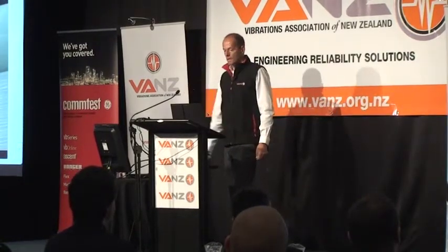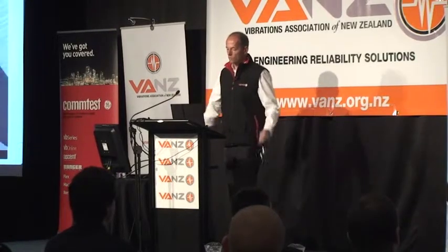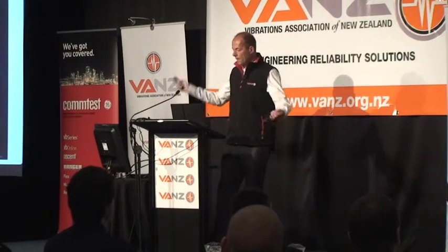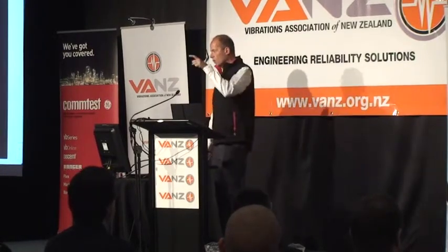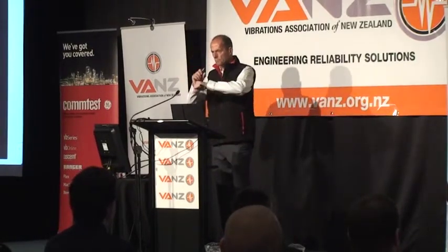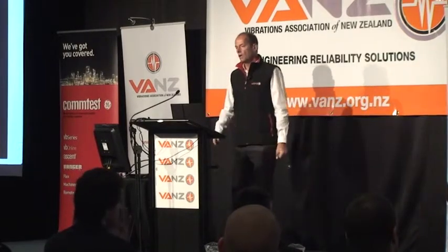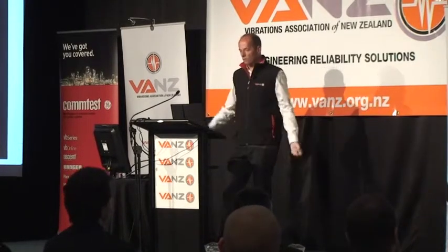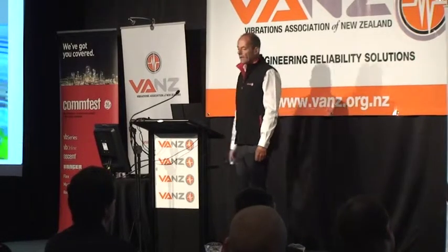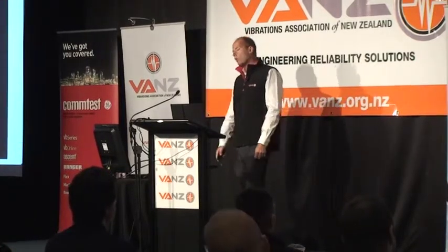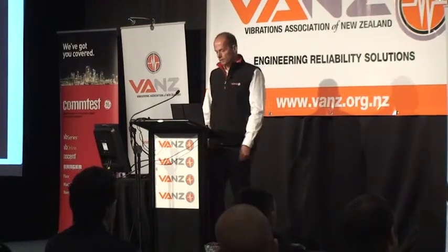And whether it's that contamination that we looked at in the bearings or gears, whether it's unbalance, whether it's the misalignment, whether it's the bearings being cocked on the shaft, or it's been hammered into place and scored the surface, or it's cocked in the housing, or it's misaligned, or we've got EDM, or we've got false Brinelling, we could keep going on and on with all the possibilities.